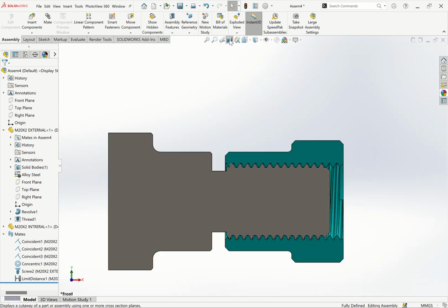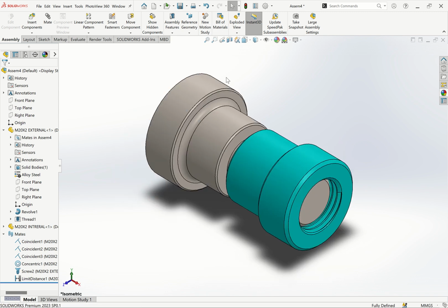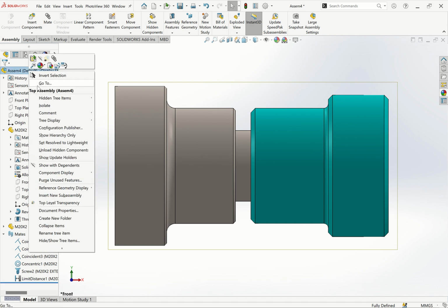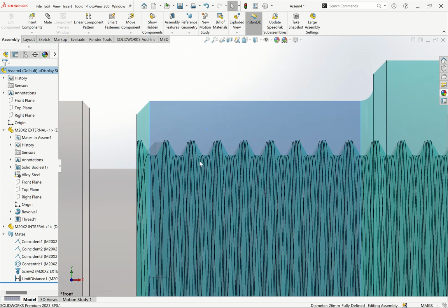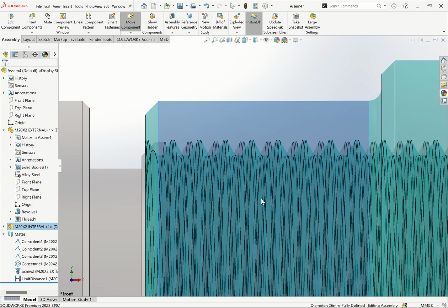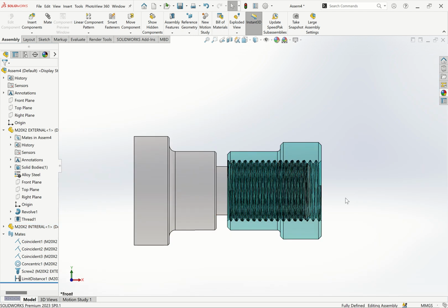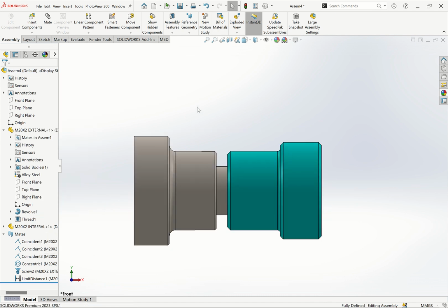So this is how we're able to design our thread in SolidWorks. Simplest way of designing thread, instead of creating those sketches, but take care of where you start from. If I do, let's say, top transparency, I'm able to see inside how the thread looks. You see now how my thread looks. If I'm opening and also closing, you see how they behave. So this is what we have learned today: how to create a simple thread, for internal and external, using M20x2, that is metric.